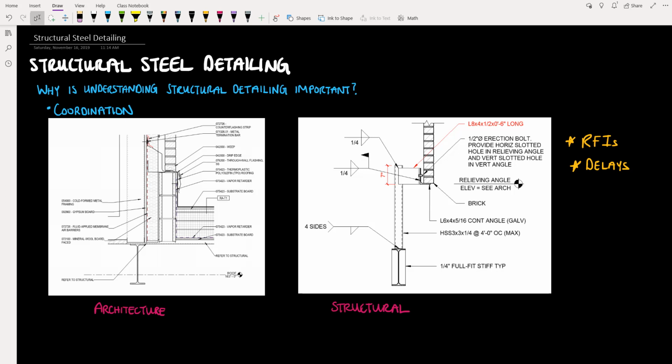Often in practice, structural engineers and architects will cut the same sections and detail views in their BIM models to define the respective scopes of work in that area. The architect will sketch in the structural engineer's detail components and create a note that says, "Refer to structural." Likewise, the structural engineer will sketch in architectural elements and add a note that says, "Refer to architectural." Occasionally, you will find that these elements that they refer to do not match up.